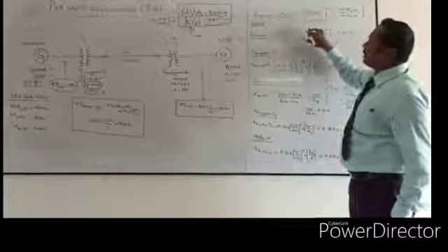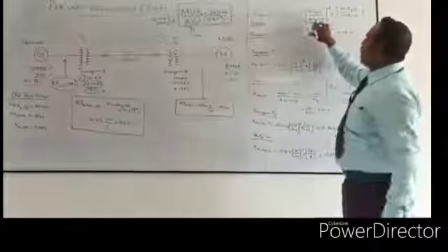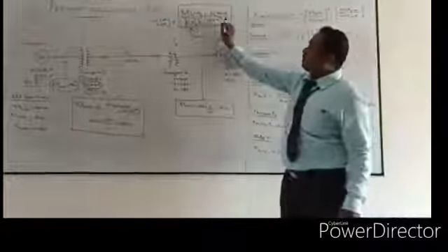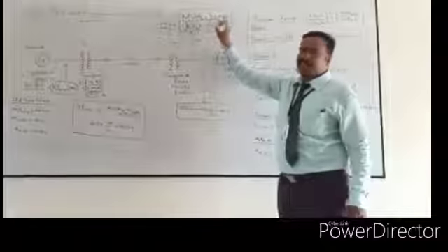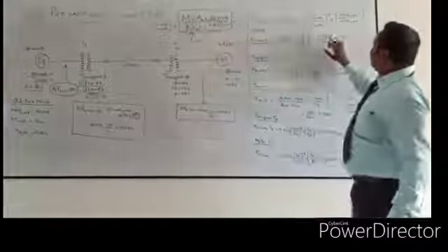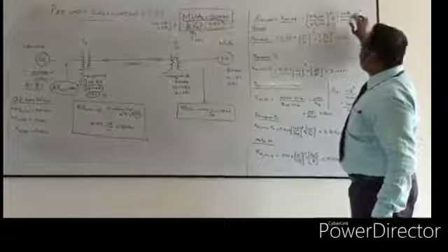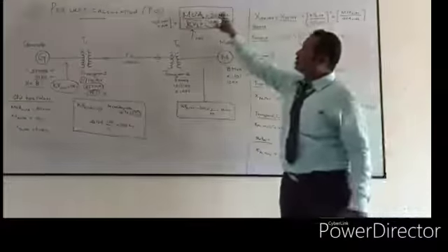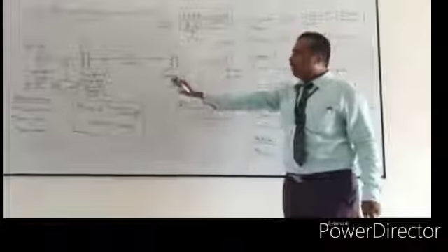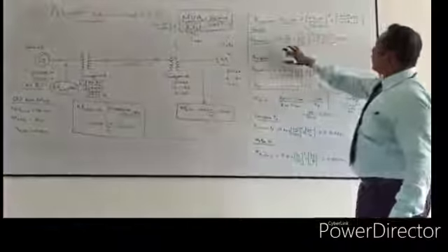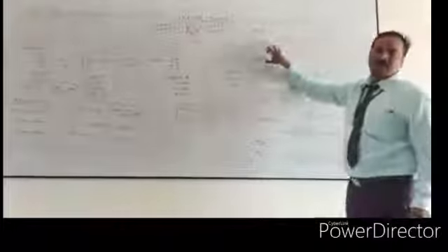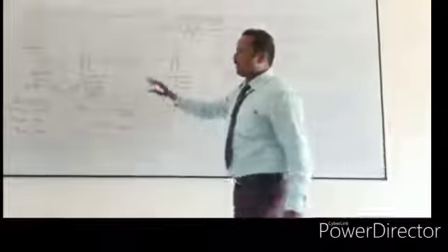So it becomes 0.08, and kV old is 10, which is the nameplate detail, and kV new is 10 kV. As per this formula, 10 kV is acting as the kV new. Next, 30 is the MVA base new. The other day I told you that this 30 MVA is going to act as a common base value for all the components present in the power system. So 30 by 30, and finally you get 0.08 per unit as the new per unit value for the generator. Next we come to the transformer section.